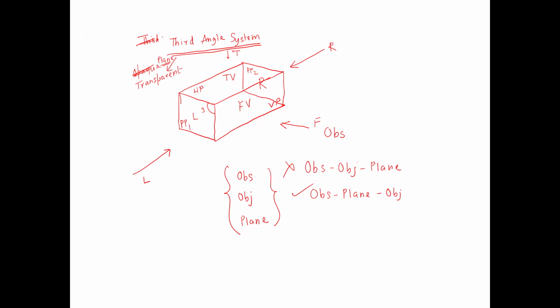So now we have obtained the projected views on the respective planes of projection. Now we have to do the rotation of the planes. So which planes will rotate? Again, horizontal plane will rotate, profile plane 1 will rotate, profile plane 2 will rotate through an angle of 90 degree, and after rotation they will align with the vertical plane. What is the direction of rotation? The direction of rotation should be such that now the third quadrant should become bigger. Third quadrant should open out.